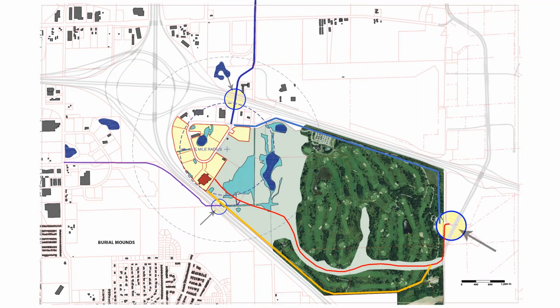It's impacting where parking would be, how big of a project they could build, views to and from the highway, and natural resources. So there's a lot of different factors that go into play before you really want to start siting a building, because if you just start on a site plan and start drawing floor plans, you're likely to end up backtracking further on in the project.